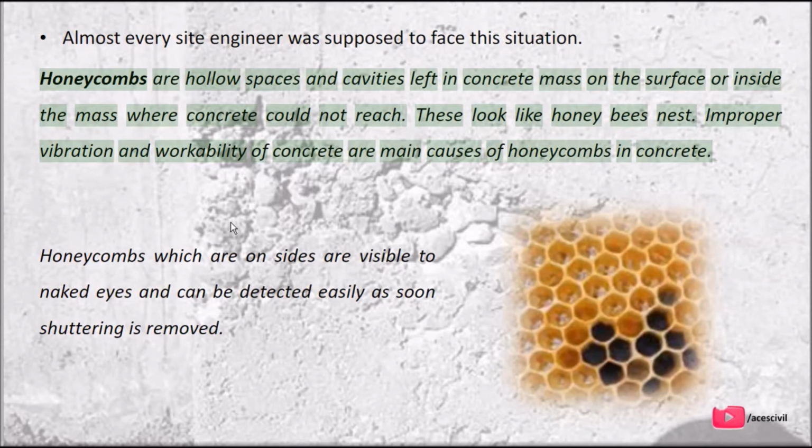Honeycombs are hollow spaces and cavities left in the concrete mass, on the surface or inside the mass, where concrete could not reach. These look like honey bees' nest. Improper vibration and workability of concrete are the main causes of honeycombs in concrete.